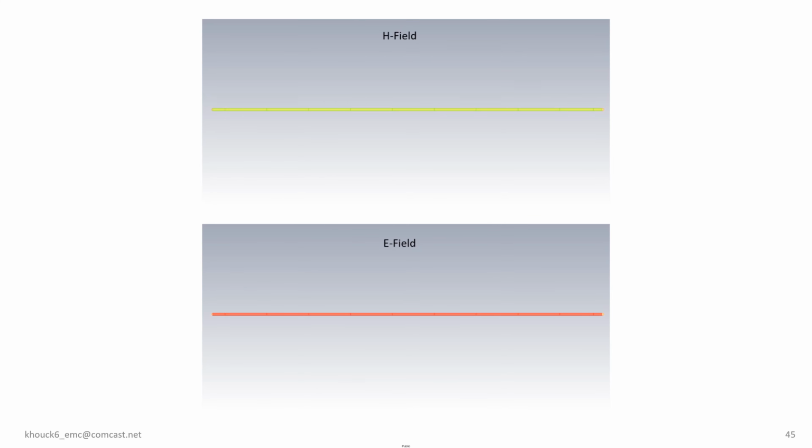When the termination impedance exceeds that of the transmission line, any change in the electric field is amplified, with the change in the magnetic field occurring in the opposite direction. In scenarios where the source voltage is fixed, any alteration in the incoming electric field strength corresponds to a change in the outgoing electric field strength and a corresponding change in the magnetic field in the same direction. These reflections continue to oscillate back and forth until the source voltage and current equal the termination voltage and current, ensuring signal equilibrium.